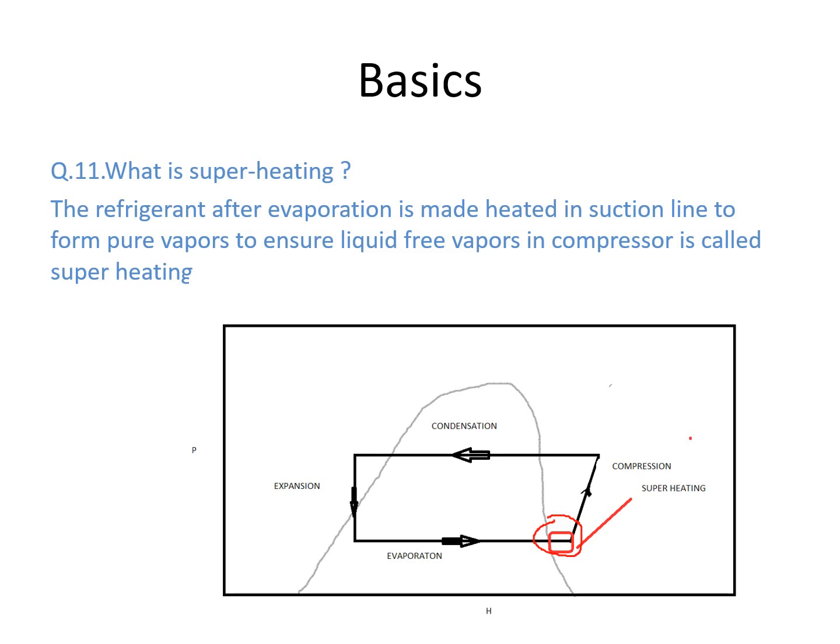In industry, there are two basic requirements for superheating. First, there should not be any liquid particles or liquid phase of the refrigerant going into the compressor, because it may damage the walls of the compressor. Another is that superheat ensures moisture, which is not part of the refrigerant, will not go to the compressor. There is a term called degree of superheat. If you want, you can go through the terms in the book and you may understand.